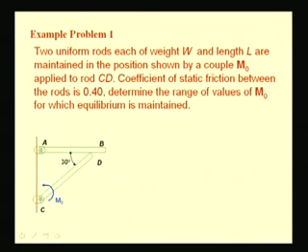We see that if this moment is large, then this rod CD starts rotating in the counterclockwise direction, thereby this point D starts moving against this rod AB towards A. If this moment M is small and is not able to support these loads, then this rod CD starts to rotate in the clockwise direction, thereby this point of contact D moves from A to B. So, we can consider the impending motion in the clockwise and counterclockwise direction in order to find the moments that are required.